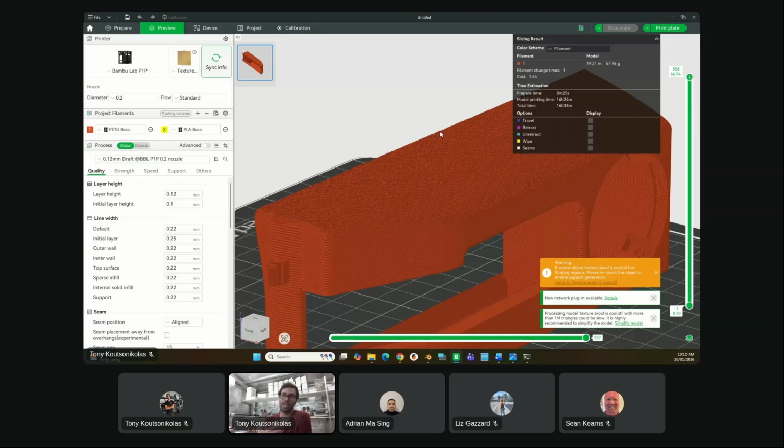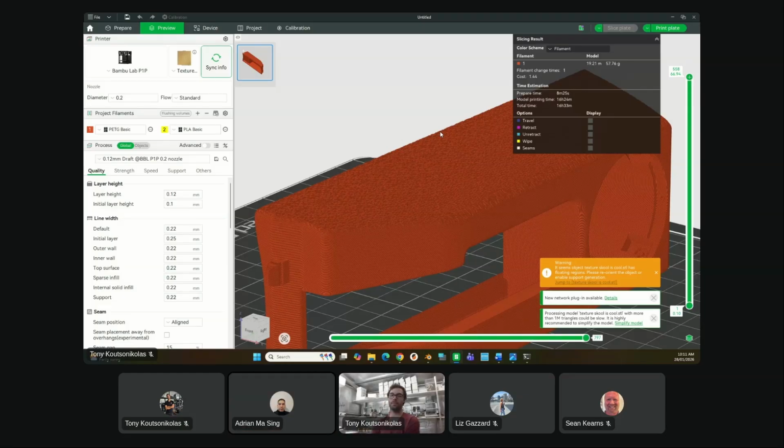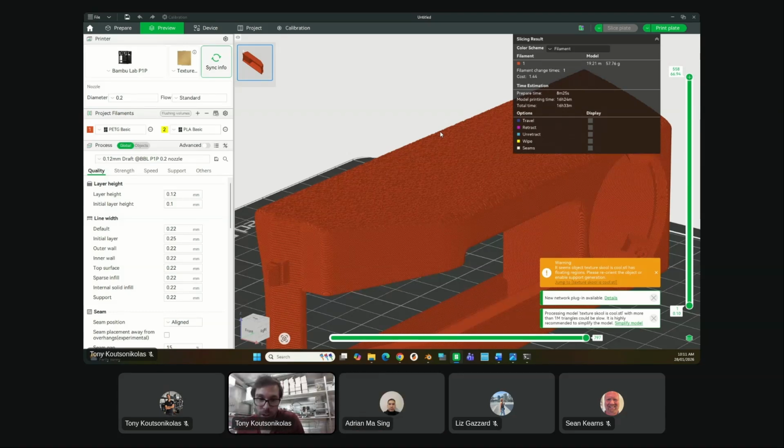What I was going to suggest is, if you want a different surface to have that texture, maybe that's an insertable plate or something like that. You print it in the correct, or optimal, orientation, and then it inserts into that part. Arguably, could you print a first layer with a texture which is really thin and flexible, and then almost glue it on, like a veneer? Yeah, maybe. It'll just depend on your part.